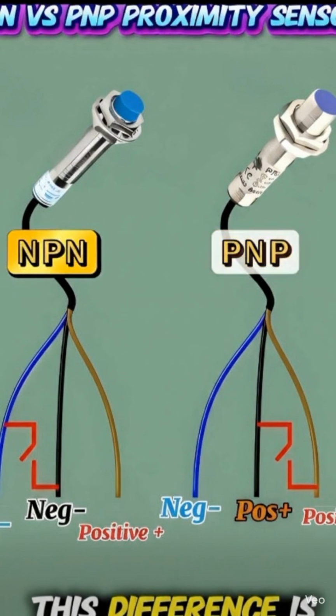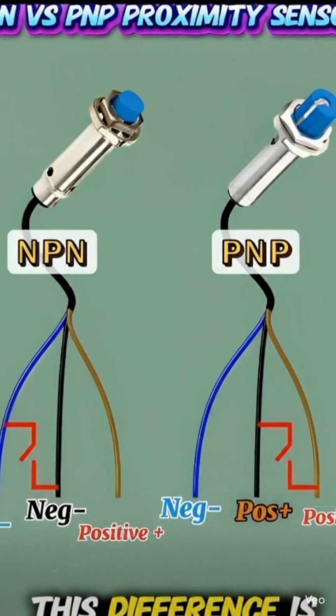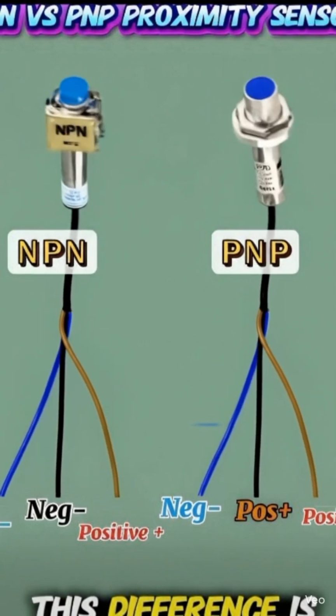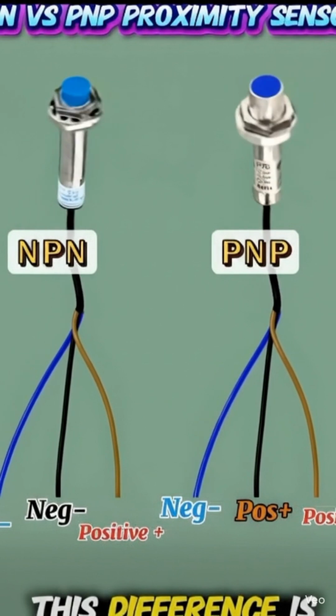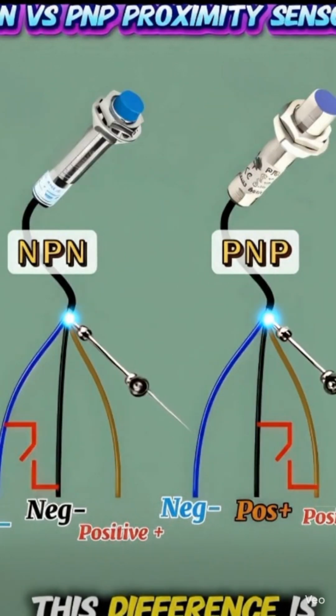4. Typical circuit connections. NPN is very common. Emitter → ground, 0 V. Collector → load → positive supply. Base → control signal; a positive voltage turns it on. PNP: Emitter → positive supply. Collector → load → ground. Base → control signal; a lower voltage turns it on.